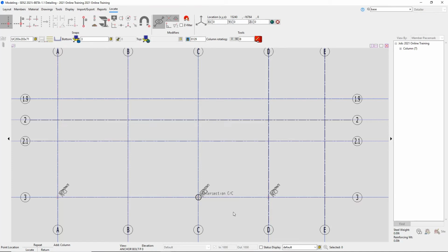At A2 and B3, we see we have the same section size, but if you look at our rotations, they are following a 90-degree rotation. So what we can do is we can come up here, we can specify our 90-degree rotation, and we don't have to change anything else because we're using the same section size and they're going up to the same elevation.